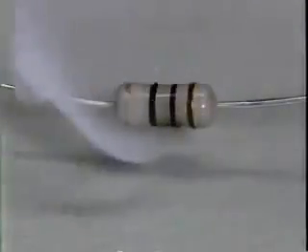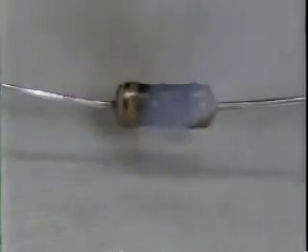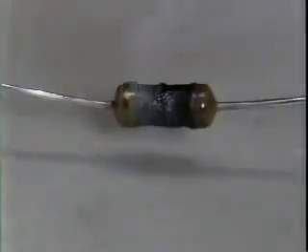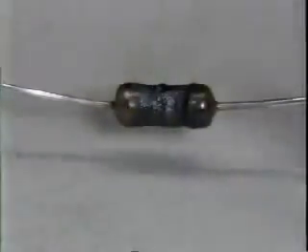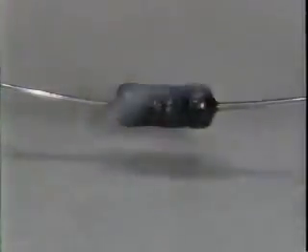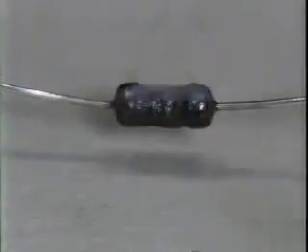Since resistors limit the flow of electricity, electrical friction causes heat to build up within the component. The resistor must be large enough to dissipate this heat to the surrounding environment without changing its own characteristic value beyond the tolerance allowed. It is usually best to operate a resistor well below its wattage rating, particularly if components are crowded on a circuit, or if there's little or no ventilation.